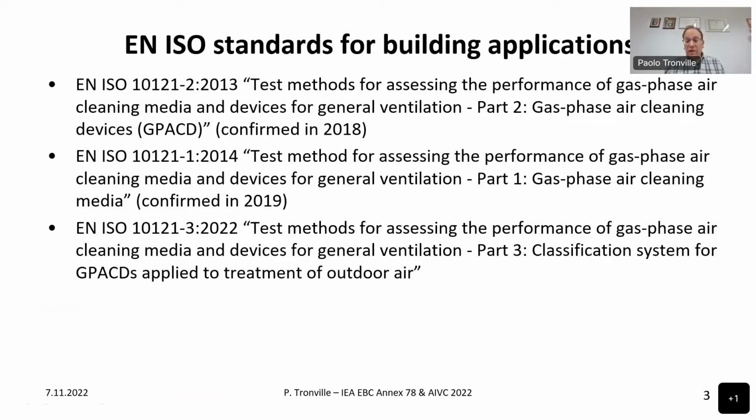Very recently, we have part 3 that was published a few weeks ago, and this is also a very important one because the test methods for assessing the performance of gas phase cleaning media and devices need a classification system. Why? Because without a classification system, it is not possible to specify easily what kind of gas phase device should be installed in a ventilation system.